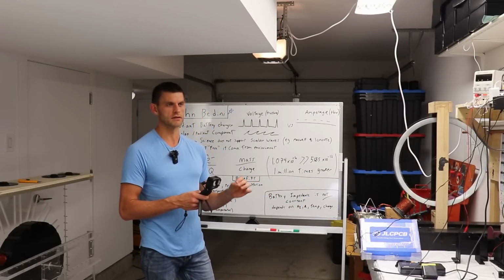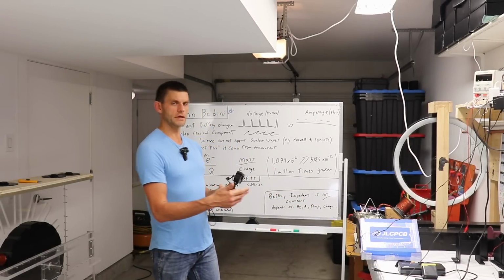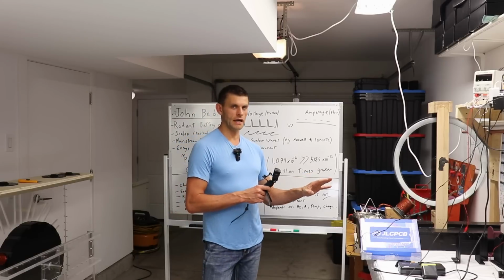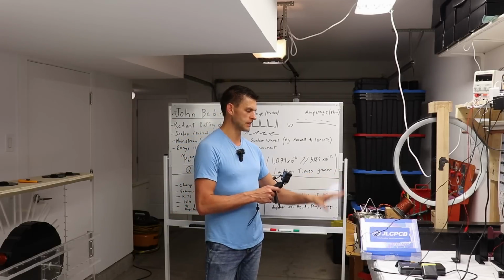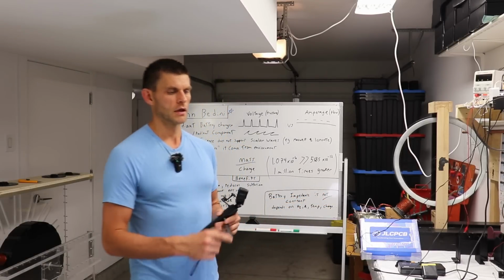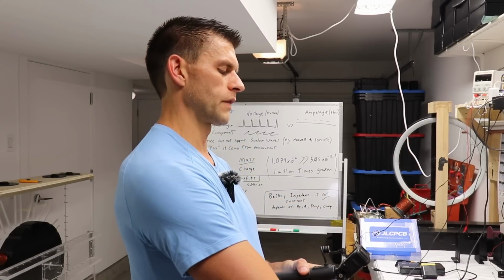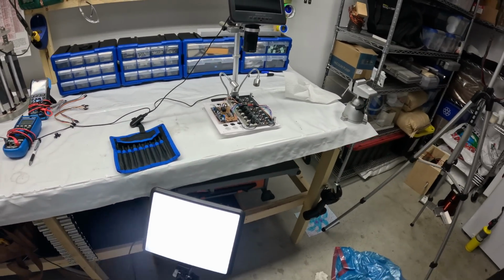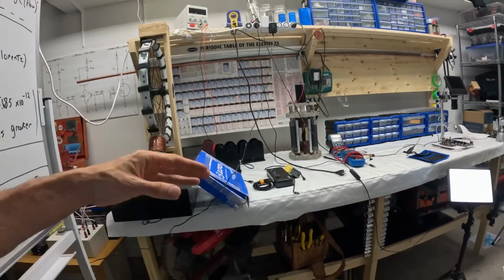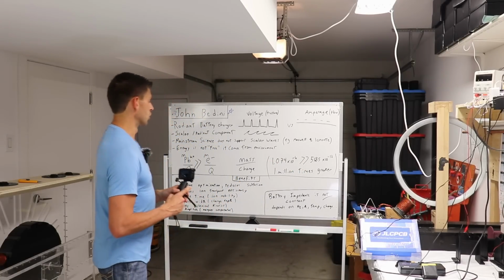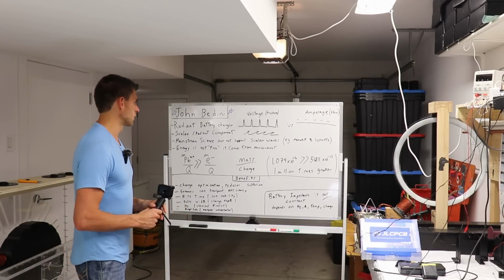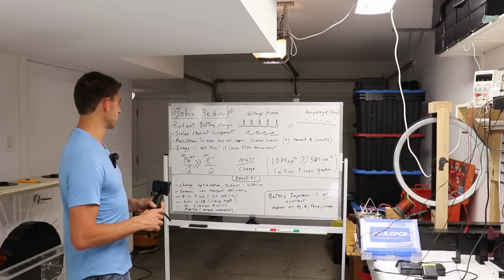If you think of electricity as water, then the voltage is pressure, the flow or the amperage is flow. And if we stick with that analogy or metaphor, then basically these BJTs use flow as the switch. They require amperage to switch them on. And then these N-channel FETs, the MOSFETs, are a pressure sensitive switch, while this is more of a flow sensitive switch. So flow, pressure, that's the difference in the switching that we're using for these two devices. And again, it's just a high level overview. If you get technical, the water analogy doesn't really hold true, but I think for beginners and just to keep everything clear, it's a good way of looking at it.